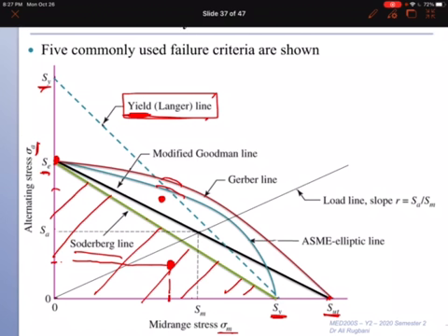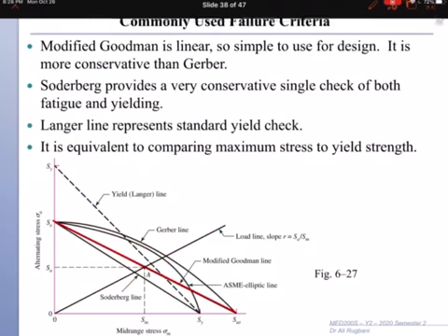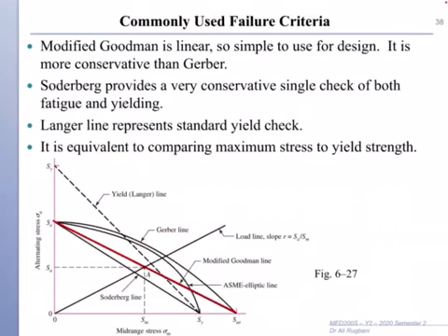Here we have a load line or a slope for a point that is here. For any point, it will give you the safety factor for that point. You connect your point with a 0 and you can solve and estimate the life.